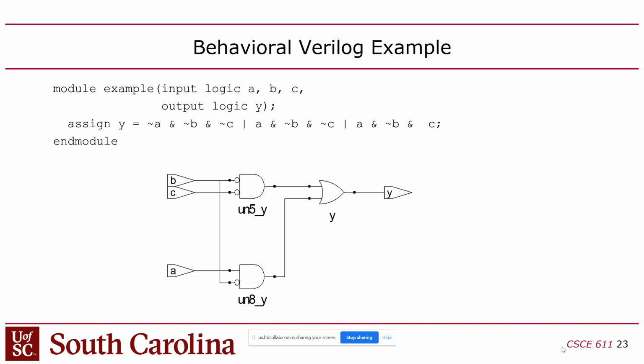And you might notice, wait a second, hold on here. 1, 2, 3, 4, 5, 6. There should be 6 AND gates in there. I only see 2. Yes? Pick the simplest possible number of logic gates. Right, it minimized it. That's right. While you were talking, I was kind of working it out. I have it right here. Yep, the simplest number. So it minimized it. Now you may get different results though. You don't know how it's going to minimize it.